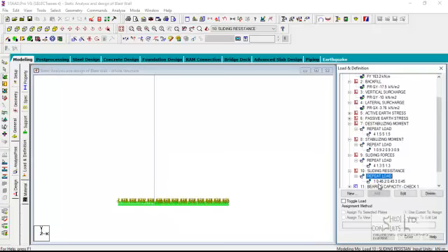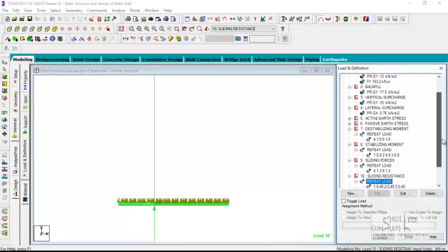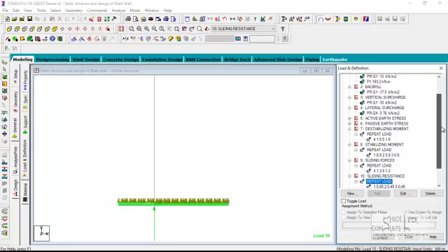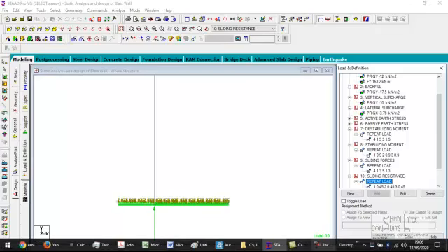We have 0.45 times the normal reaction. Normal reaction are the vertical forces that provide normal reaction, which are load case 1, 2, and 3: the dead load, the backfill load, and then the vertical surcharge.